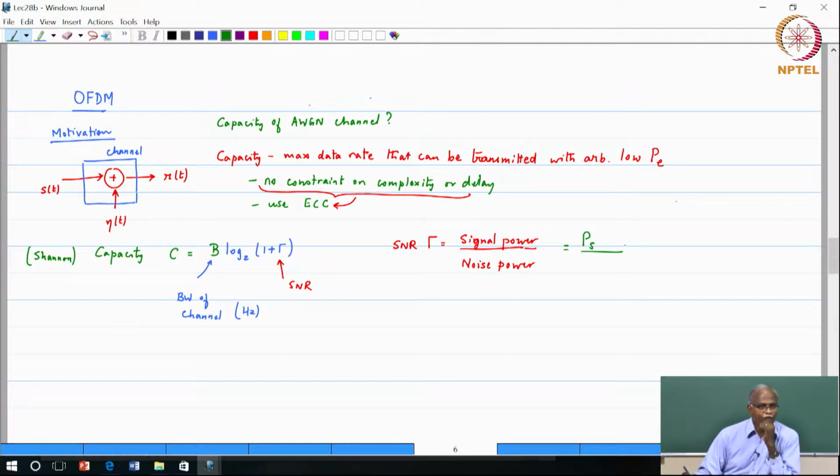Now noise is something we do not control; it is in the electronics of the system that we are using. The assumption is that it is white, that means it has a flat spectrum. So what portion of the noise will come in? Whatever your signal bandwidth is, your receive filter will allow that noise to come in. If you have a signal of the following form, minus B to B, complex baseband, you would have to allow a filter of bandwidth minus B to B.